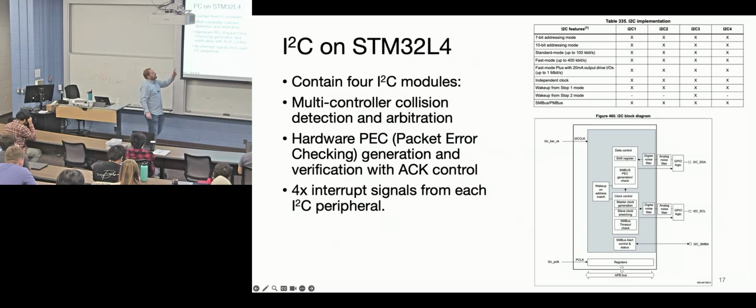And so this allows you to at least have 3. There are I2C address translators, chips that you can put in between that will translate one address to another address, and that will allow you to have multiple of the same chip on a bus. But it just becomes harder to use, yes.